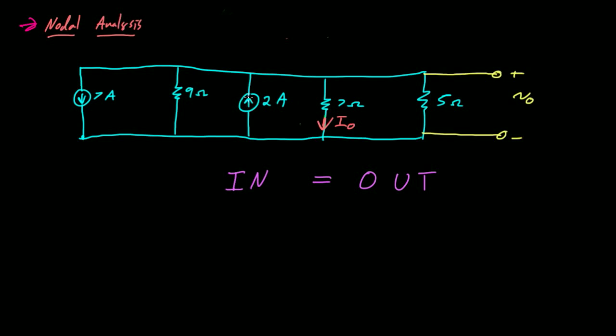Now, I should say that we are assuming in these circuits, and it's a pretty valid assumption, that we're not going to have charge build up at any point inside of one of these nodes. If we had a buildup of charge somewhere, then we couldn't say that what came in equals what goes out, because we could be building up charge. Typically that doesn't happen in a circuit. When it does happen, it means that you've got some amount of capacitance, which we will talk about in future videos. And you'll definitely learn about it more as you progress in any circuits class that you're taking.